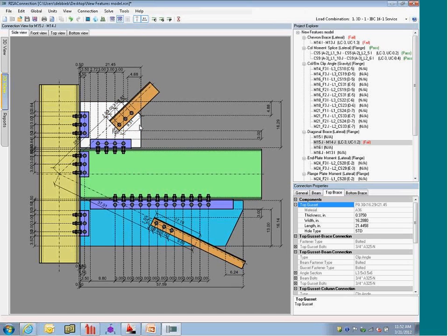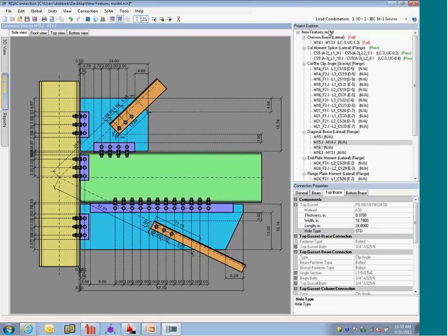Okay, so if I have some edge distance, maybe I need to increase this up here. So just click on that 21.45 and adjust it. Maybe it needs to go to 24, for example, and you can rerun the solution.